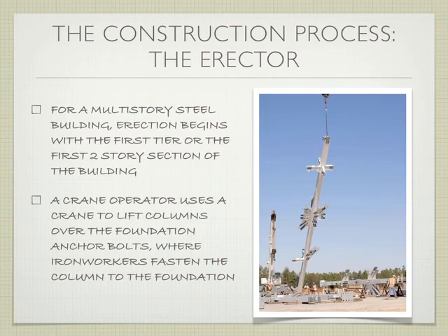Versus the tolerance requirements in concrete. Typically on a residential construction job in concrete, the tolerance requirements for where you place an anchor bolt for tying a mud sill into a foundation are plus or minus 2 inches. Pretty generous.